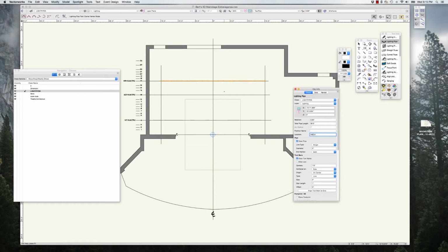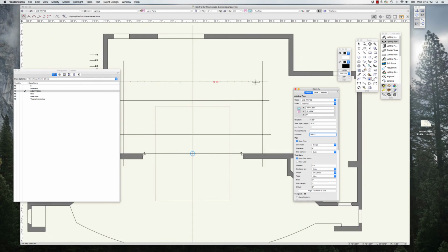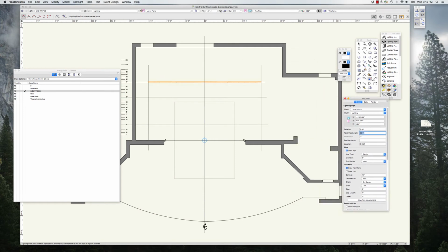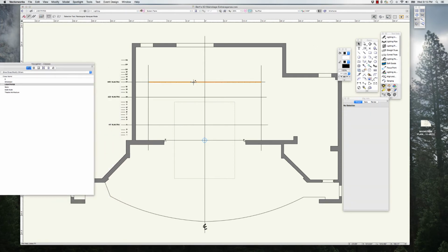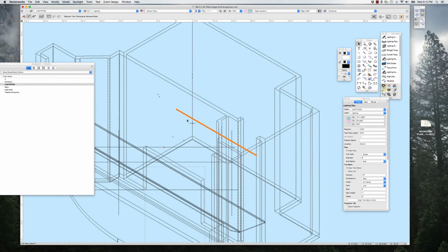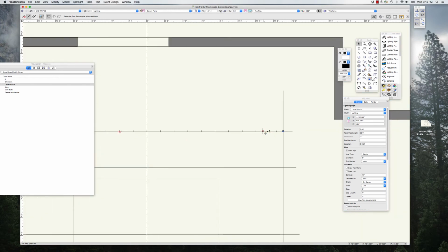And these pipes are inherently hybrid objects, so it's drawing just a line in 2D here, but when I go to 3D, it actually draws the pipe, and so I can give it a height. Our proscenium was 14 feet tall. I set the electrics at, I don't know, 16 feet. Seems like a reasonable place to start. So then if we look at this, and I'm going to highlight this, and front view, you'll see that, actually let's go to isometric. You can see that we have a 3D pipe 16 feet above the ground, but in 2D we have the representation of the electric.